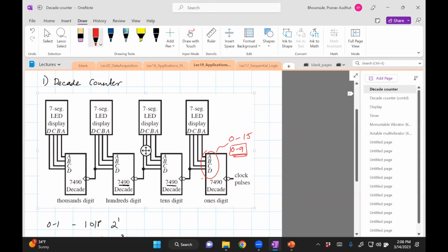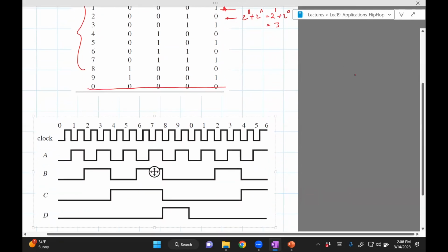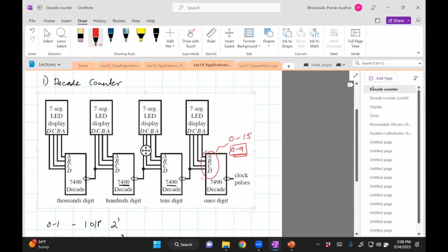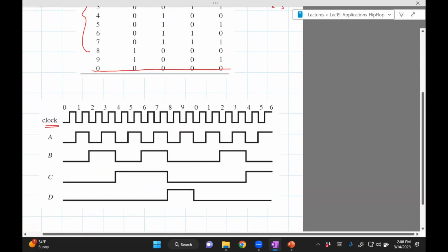Okay. Now, how does this work? Well, what you need is a clock signal, just like you need it for flip-flops. This is the clock, which goes into, this is just explaining one of these counters, just how this works. So you'll supply this with a clock, and in this case, it is negative edge triggered, as you saw in the symbol. So every time the clock goes through a negative trigger, it will trigger A. Next one, second trigger, and so on.